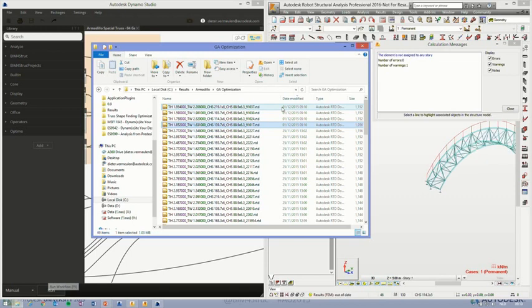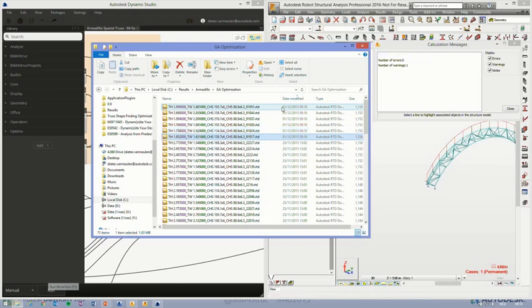We have to assign a number of population. So we have to start with, let's say, Adam and Eve, yeah? And we have to know how many of them should start. So I decided to start with 10 people, 10 specific trusses, and work with that. Work with those guys and make babies of it and make a few generations, and those few generations are the iterations. So in this case, it's easy to count. You have 10 populations, 10 iterations, so it will return 100 models. Yeah? But 10 iterations are 10 generations, so